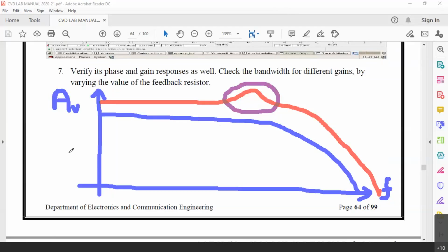The overshoot is basically the non-ideality of the devices. As the devices have their own parasitics, all the devices become frequency selective. In the sense, in the high frequency ranges, the devices will not obey any of those laws which we actually frame about it. Even the models which we have in the Cadence library may not be completely accurate even in high frequencies.